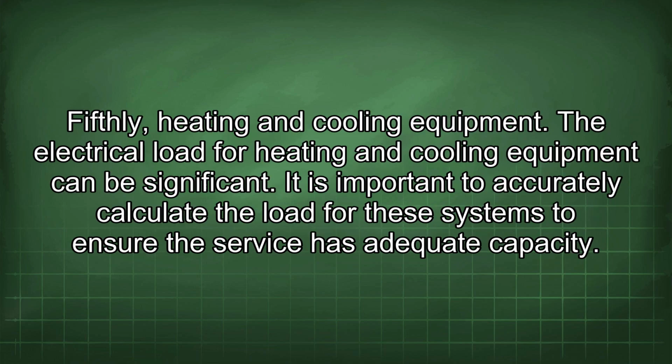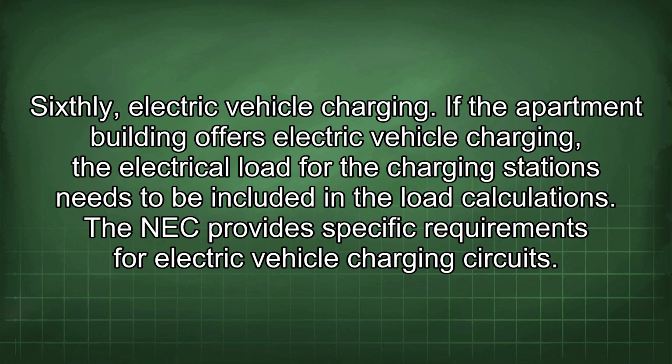Fifthly, heating and cooling equipment. The electrical load for heating and cooling equipment can be significant. It is important to accurately calculate the load for these systems to ensure the service has adequate capacity. Sixthly, electric vehicle charging. If the apartment building offers electric vehicle charging, the electrical load for the charging stations needs to be included in the load calculations. The NEC provides specific requirements for electric vehicle charging circuits.